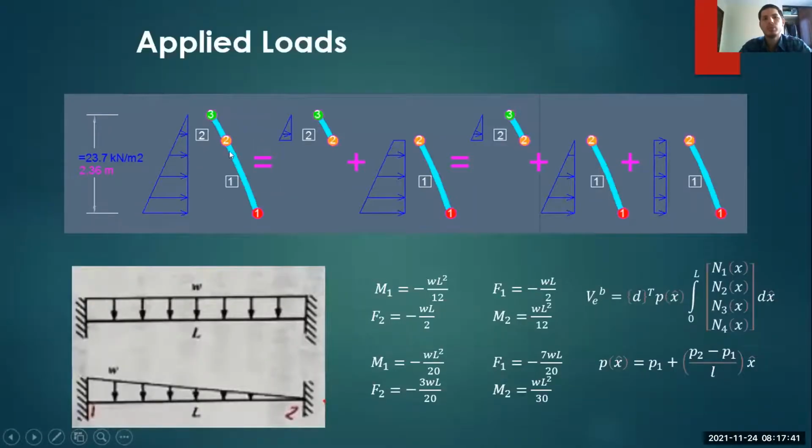The applied loads were changed to their equivalents, and the triangular load was transformed into a rectangular and triangular load again, because we had a trapezoid after the simple support reshaped the element. Here we got the equivalences by the energy method. But we can see different values for the rectangular and triangular loads.